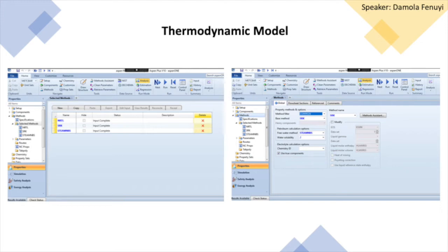In comparison, the SRK, which stands for Soave-Redlich-Kwong method, is suitable for non-polar or mildly polar mixtures, and therefore it is usually used for the processes that involve hydrocarbons, water, and air, such as in the STM system. It is also suitable for the high temperature and pressure conditions used in the STM reactions. When using the SRK method, STEAM-MBS is selected as the free water method, as the MBS steam table provides a greater accuracy, and the SRK method is designed to work with it.